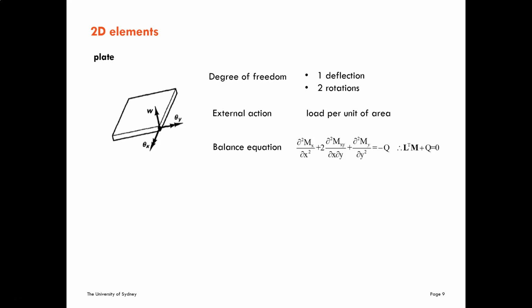The external action is a load per unit of area, that is the weight of the elephant. The balance equations are a generalization of the bending theory. I'm going to have here 3 bending moments, and they are related with Q, that is the action that is load per unit of area. The L operator is given by this differential operator.